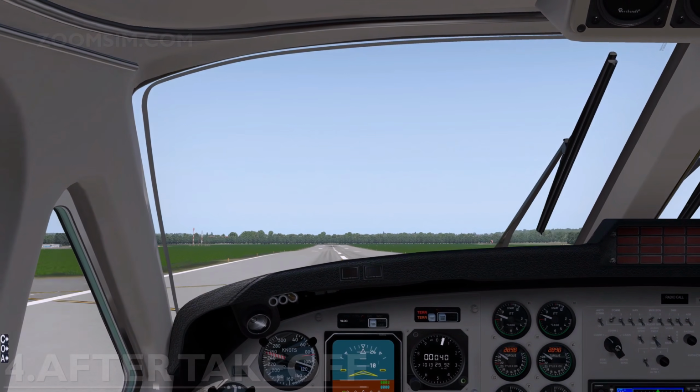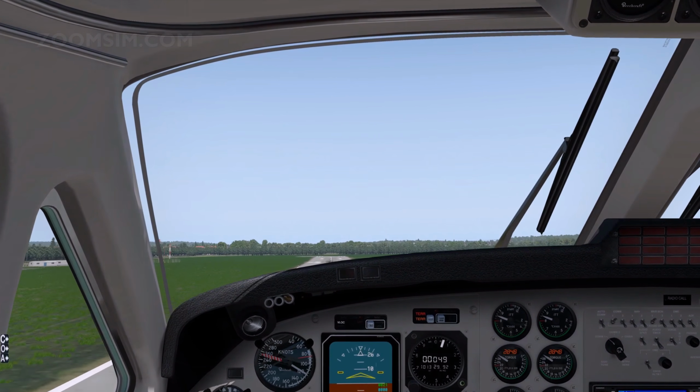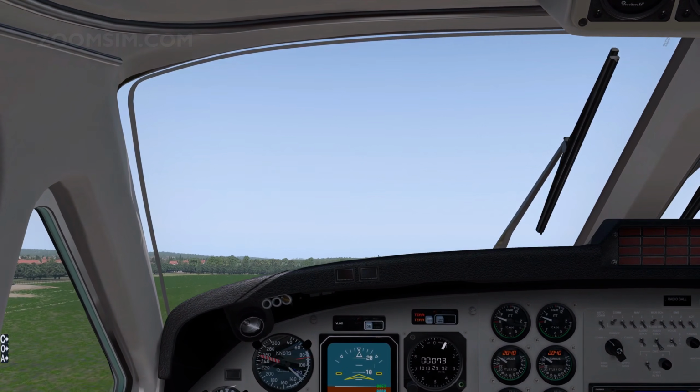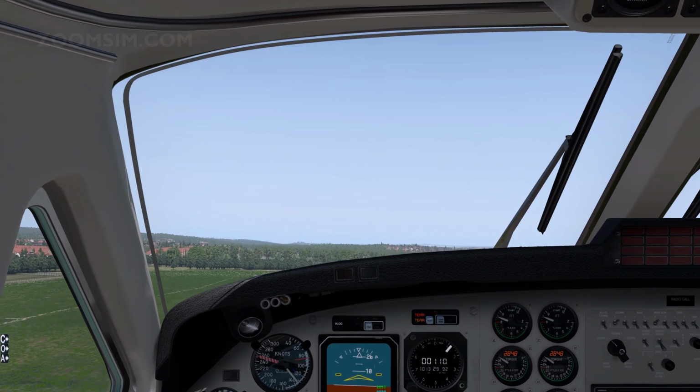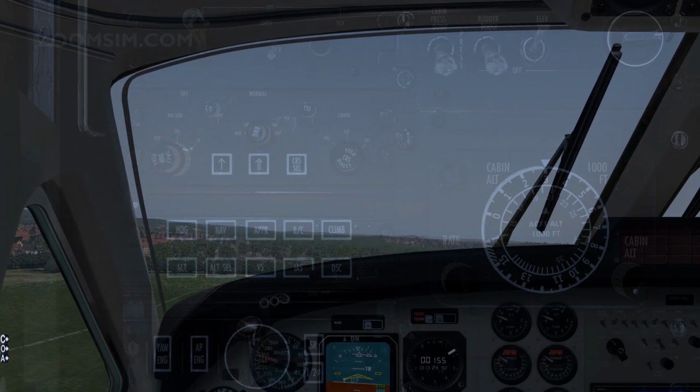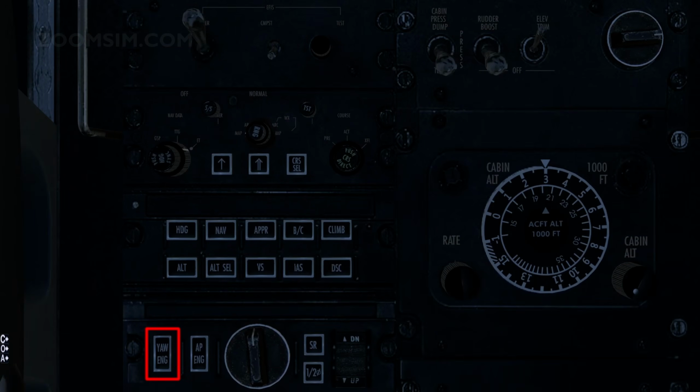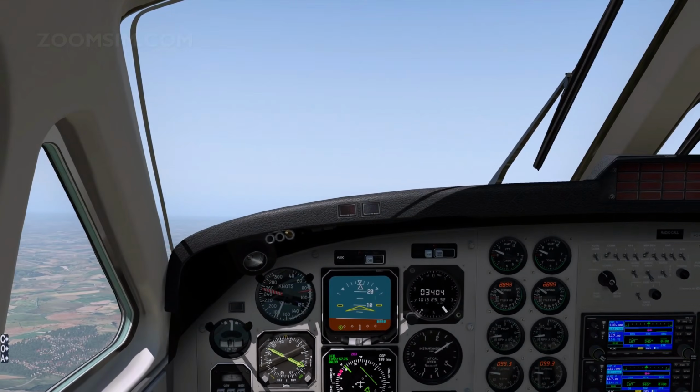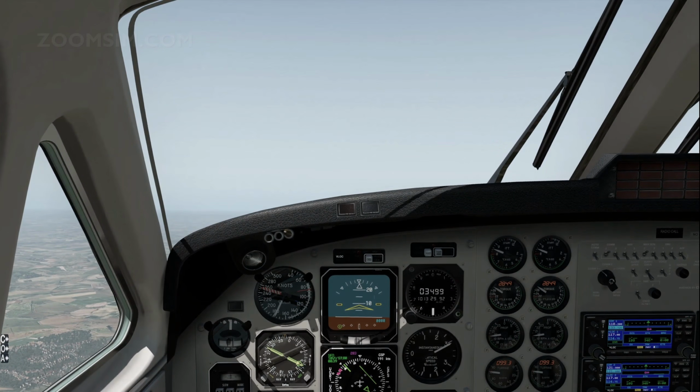Landing gear up. Flaps up. Yaw damp on. The yaw damper reduces rolling and yawing oscillations. Engines, climb power, set. Props set 1900 RPM.